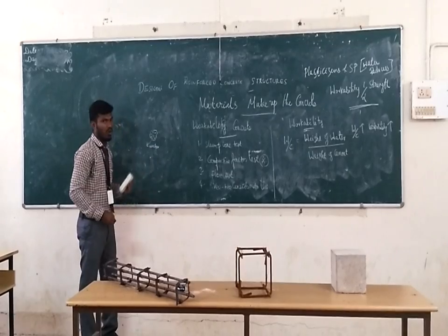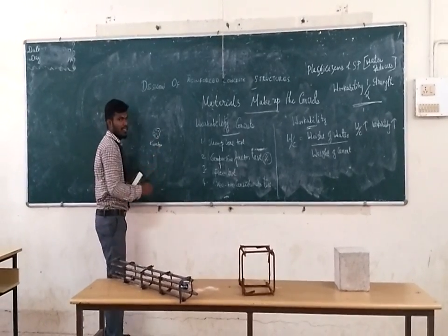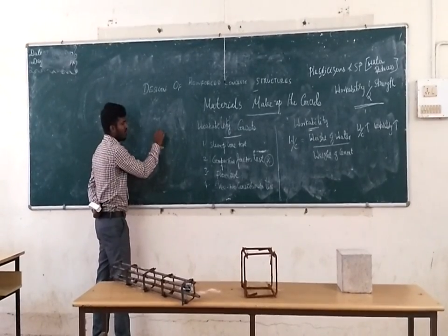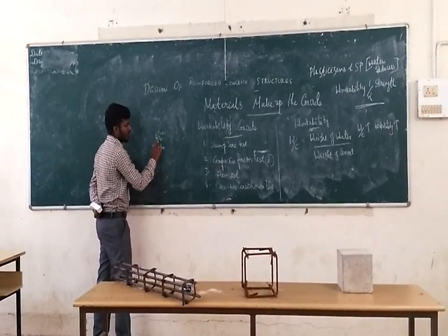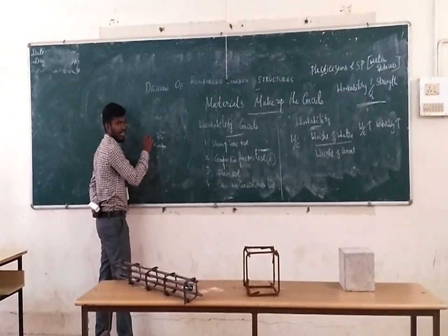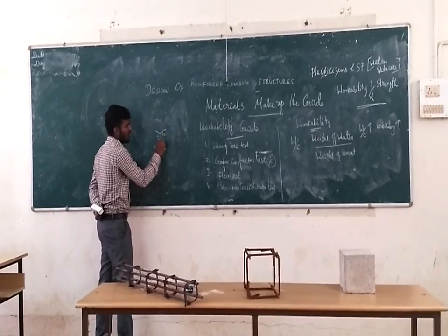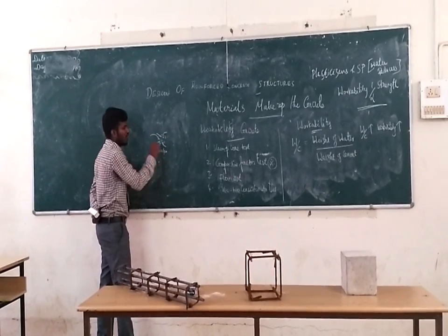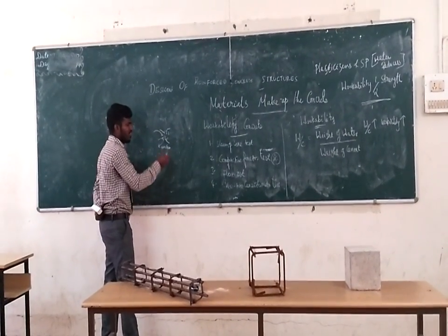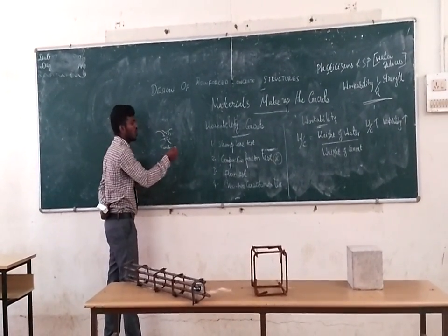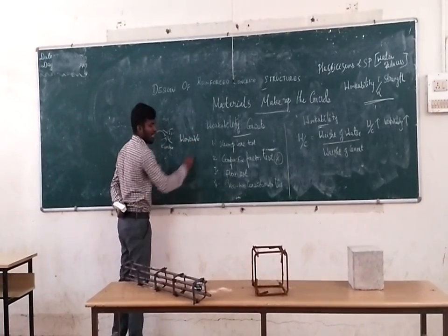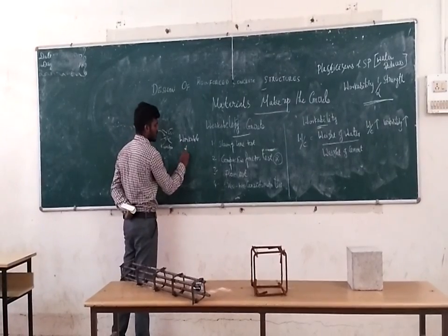We release the water by adding super plasticizers. They collapse this entrapped layer and release the water from the entrapment, so the concrete becomes more workable and also stronger.